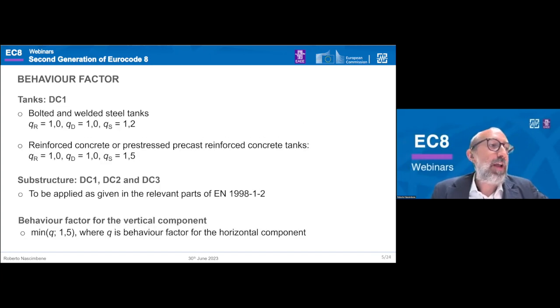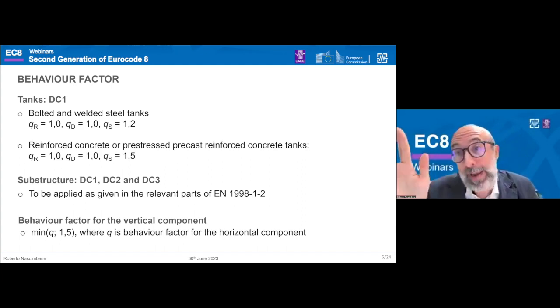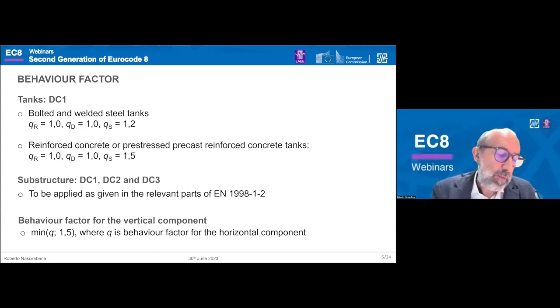Then just a few words, one slide on the behavior factor. Behavior factors also for tanks, not only for silos, are limited. Just a reminder that tanks should be designed in ductility class 1. Substructure of elevated tank can be designed also in ductility class 2 and 3, but the reminder is related to